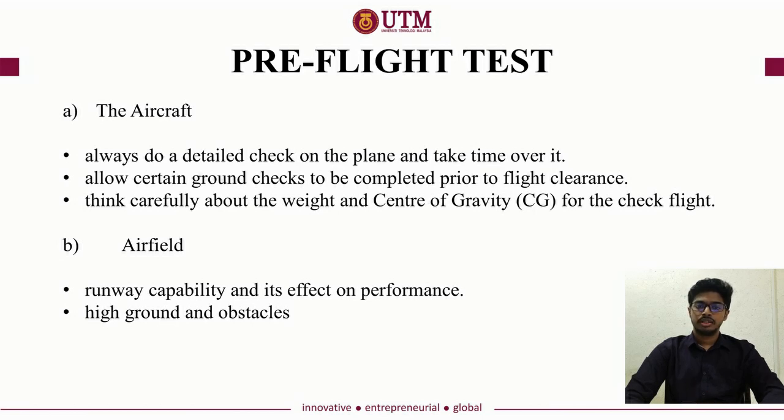The first would be the pre-flight test. Now I'd like to talk about the pre-flight test in terms of the aircraft. So we have to always do a detailed check on the plane and take time over it. This is because if the aircraft has been checked or painted, we have to pay careful attention to these activities as they can give rise to numerous technical issues such as pitot or sensor damage.